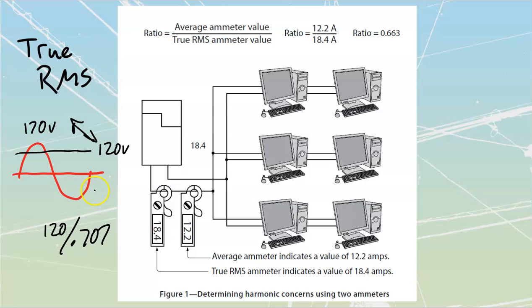This is going to be important that we remember, our value between V peak over to V RMS, because if we've got a good waveform, we should have this ratio maintained. If I don't have a good ratio maintained, let's go to third order harmonics. Under third order harmonics, I can still sometimes get 120 volts RMS, but I'm getting it off of this steep-sided double hump wave that's going to be over here.